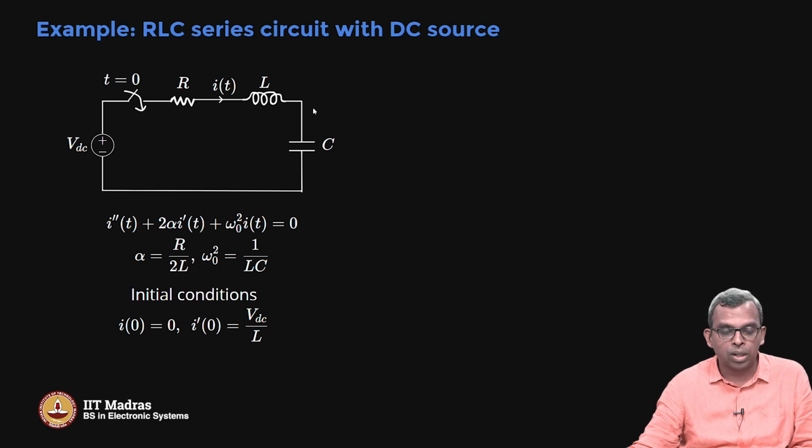Okay, so what's going to happen initially is when you turn the switch on, there's lots of circuit current and circuit loss here. For instance, the current through an inductor cannot rise suddenly, because the current needs to be continuous and differentiable, in fact. So L di by dt, or L I prime, is the voltage across the inductance. So I cannot go up suddenly, and likewise the voltage across the capacitor cannot shoot up suddenly, because the current through the capacitor is C Vc prime of t. So those rules are there.